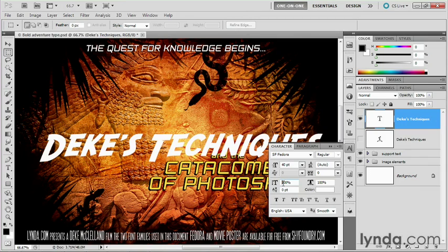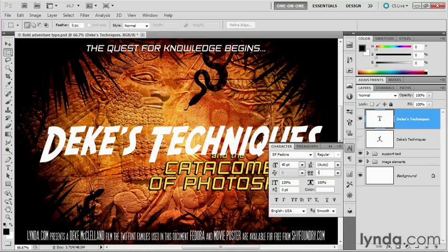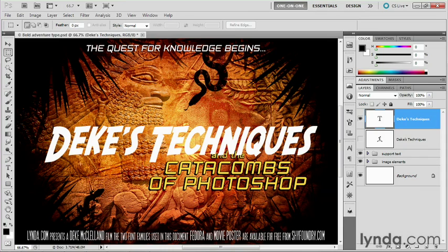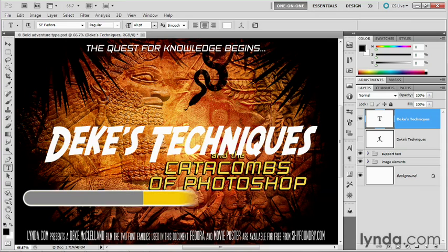All right, we're going to make a couple of changes. First, I'm going to change this vertical scale value to 130%. And then I'm going to change the tracking value to -20. And press the Enter key or the Return key on a Mac in order to apply that change. All right, that's enough formatting for now. Now I'm going to select the Type tool, which you can get by pressing the T key.